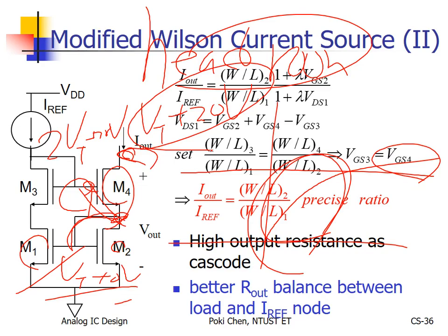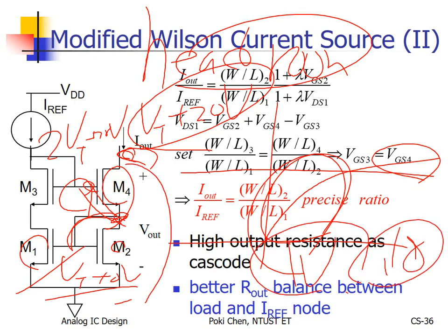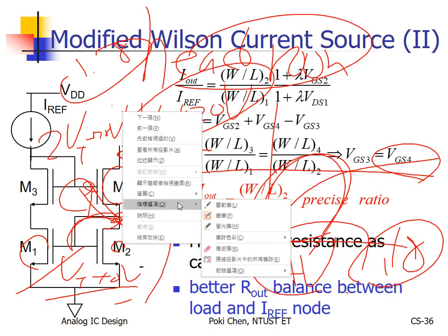For 0.18 micron, 1 VT usually means 500, 600, or 700 millivolts. And how about delta V? Usually 200 millivolts or something. So I promise you, the headroom is at least 1 volt for 0.18 micron. Okay? 1 volt for 0.18? Does it make any sense? Not much. Why? Because the VDD is only 1.8. That's it. So that is some kind of rough estimation, okay?